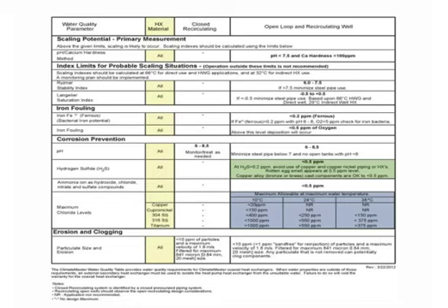So you're going to see here copper, cupronickel, stainless steel and titanium. You're going to see what those allowable limits are, parts per million, along with that rated temperature. So please be careful. If it was me and there was any amount of chloride, personally, I would put in at minimum a stainless steel braze plate heat exchanger external. We're going to show you that here in a moment.